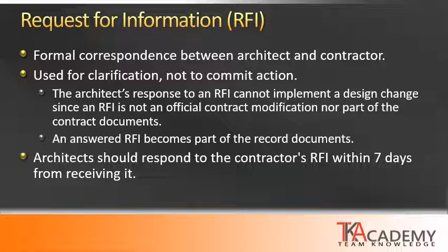The RFI cannot implement a design change because, again, the design documents are part of the contract. So an RFI response is not part of the contract. It's not an official contract modification, nor is it a part of the contract documents. So again, the RFI is simply the correspondence, the question and answer, that does not implement any type of change or modification. However, RFIs do become part of the official record documents of the project.